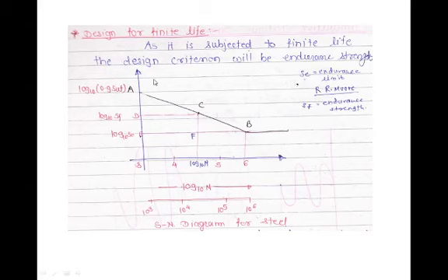The endurance strength value is below the yield limit. Irrespective of material type, for the fluctuating stresses we have to use this one. Now that is the R. R. Moore test. What is this? This is a log graph. This is log 10 of 0.9 Sut, log 10 of Sf, that is the endurance strength, and log 10 of Se, which is the endurance limit.